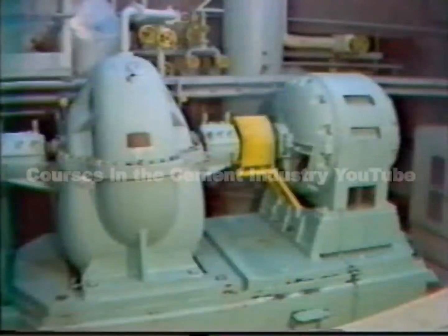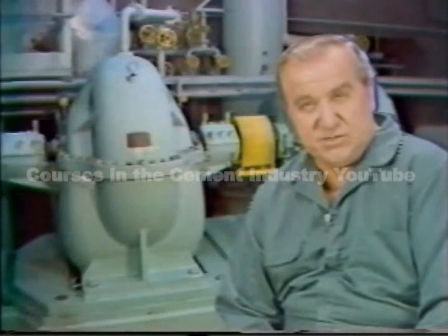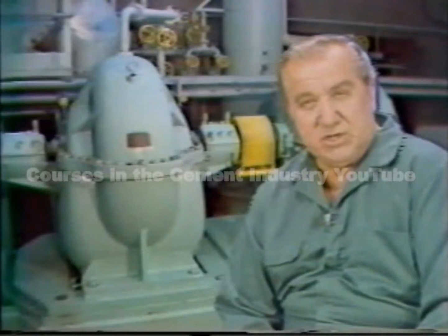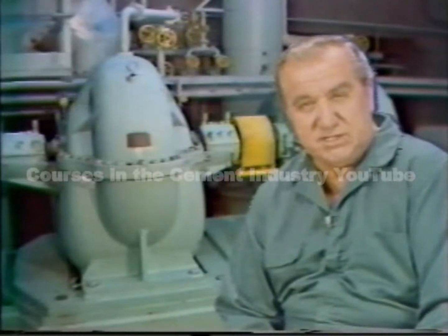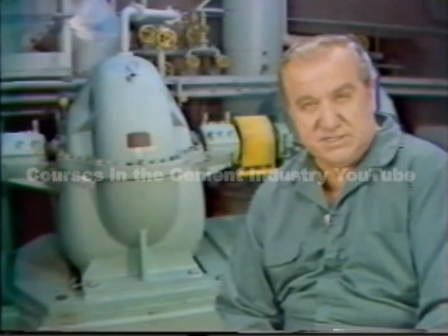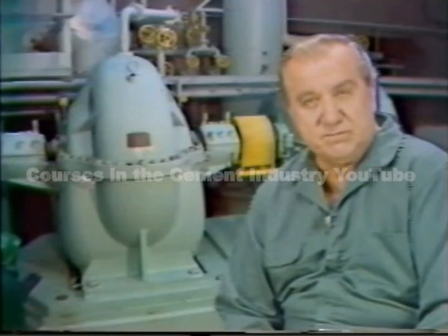When two rotating shafts are coupled together in perfect alignment, they'll turn as if they were one shaft. That's the ideal situation, and it's very difficult to do. But the closer you can come to perfect alignment, the better it is for the machines and coupling. Even though most couplings are flexible enough to handle small amounts of misalignment, they'll last a lot longer if you approach perfect alignment.